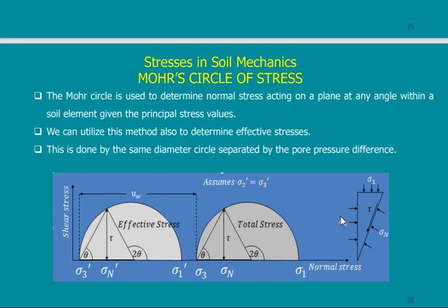But this normal stress will cause shear stress. Why? Because this normal stress wants to penetrate the soil and go deeper. What prevents it? The neighboring soil. This footing is on top of the soil. It wants to shear the soil and go down. What prevents it from shearing the soil and going down? Particles around it. Suppose that I'm putting this mobile, which represents the footing, in water.